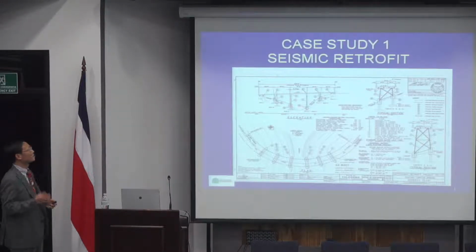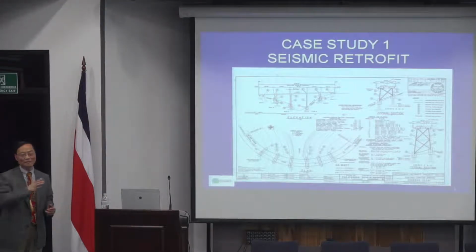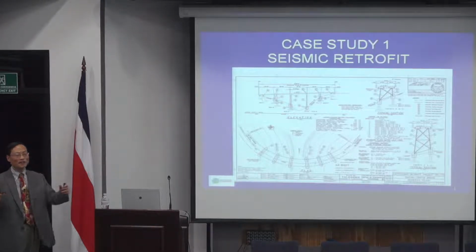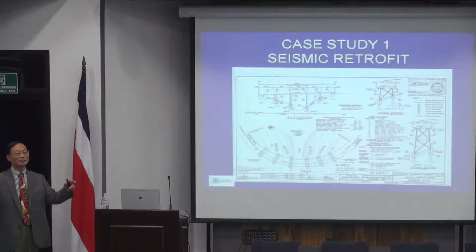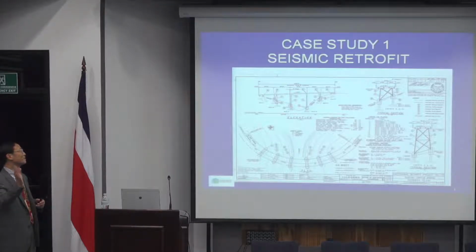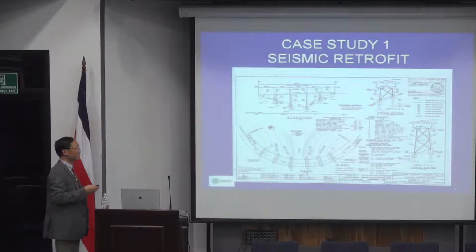so it's like if you have simply individual piers, and the earthquake load, no matter which direction you apply, you may have a problem of torsion, which at the abutment will have very large deformation, and at each pier it may have not only a longitudinal and transverse, but also torsional load. So that's why the structure analysis becomes complex.